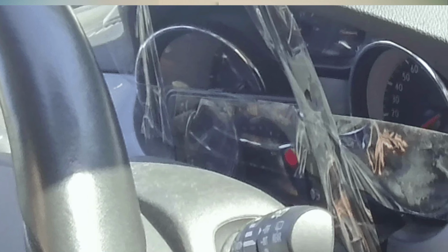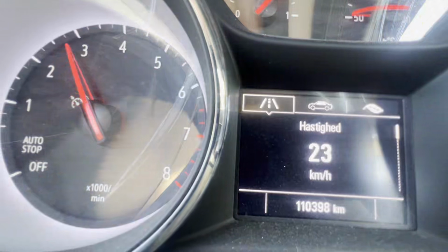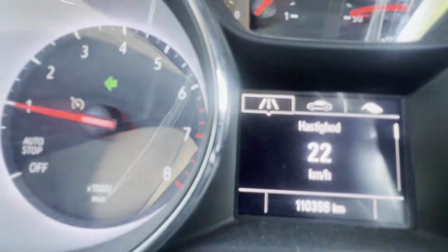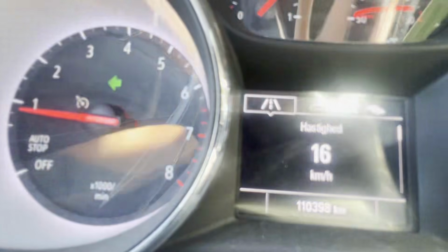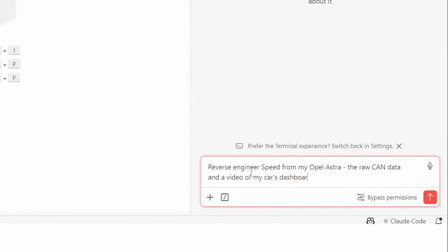And in my opinion, that is the OCR method, where you record a digital value of the signal from your car's dashboard, for example, with an iPhone, or better, I would say, with a webcam that is synchronized to your PC time, and thereby the CANsub's time. And you can essentially record this data while you are driving around. And in my experience, you want to do this, if possible, later in the day, so there's not too much sunlight. And you would also want to do it in a way where the webcam is quite stably positioned in order to minimize the drift. But I did the worst case scenario, and it turns out that Claude and the script utilities are able to handle this pretty much perfectly well.